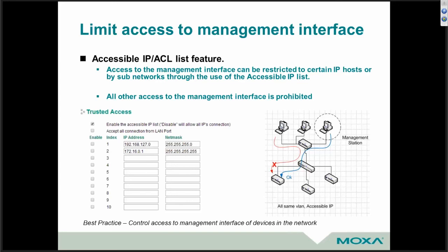Many control systems are designed around a flat layer 2 network, which means that they can't use separate VLANs and more advanced topology methods to accomplish this. So the accessible IP list is a way to limit the scope in this situation, as well as a mitigation against attack.